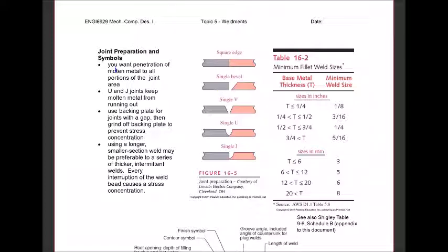We also, if we can, would rather have a longer, continuous, smaller weld than a bunch of thick welds, because every weld, beginning and ending, causes a stress concentration.